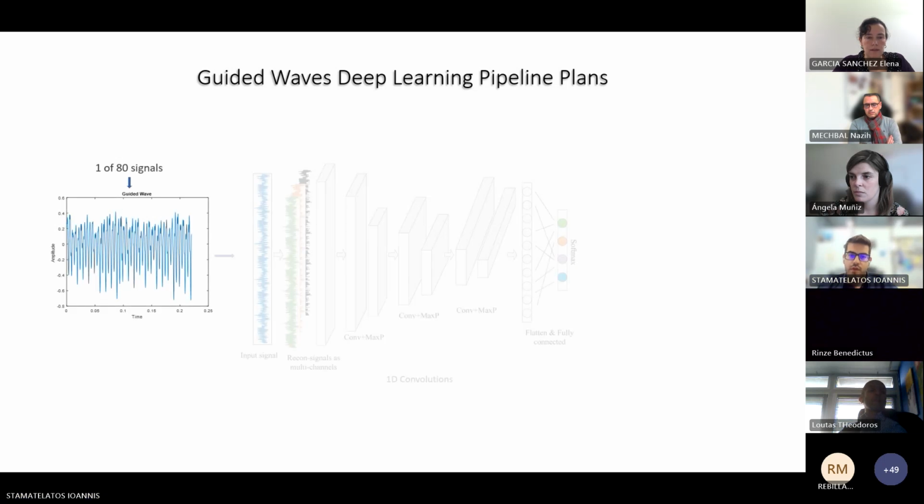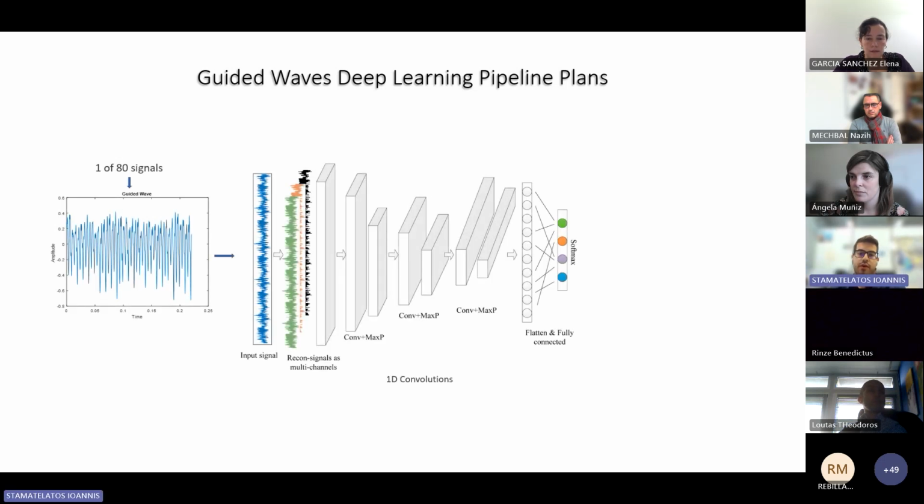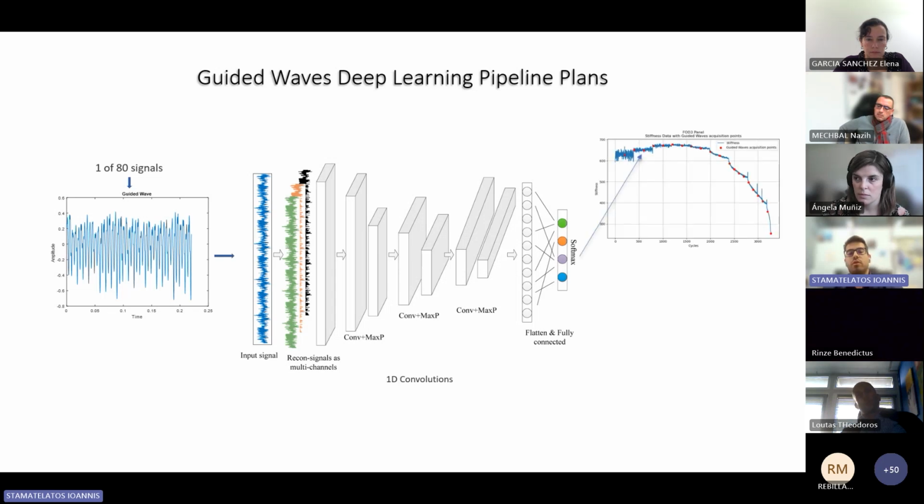We haven't yet finished running the models, but we already know how we will approach this. We will insert each of these 200 signals for each point through some convolutional layers in order to extract meaningful features. And then each of these we will map with the stiffness value or the remaining useful life value, in the same approach that was done for strain.